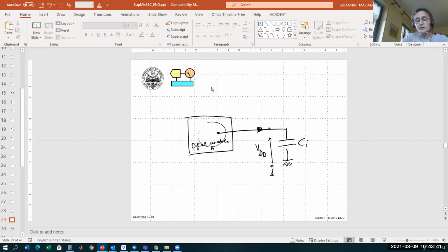what do we have here? The output interface, as we learned, is always PMOS that allows the connection to VDD, and NMOS. This PMOS can be just one PMOS or many that stay in series or in parallel. But anyhow, you have PMOS that are connected to VDD and NMOS that are connected to ground. And then you have your output.